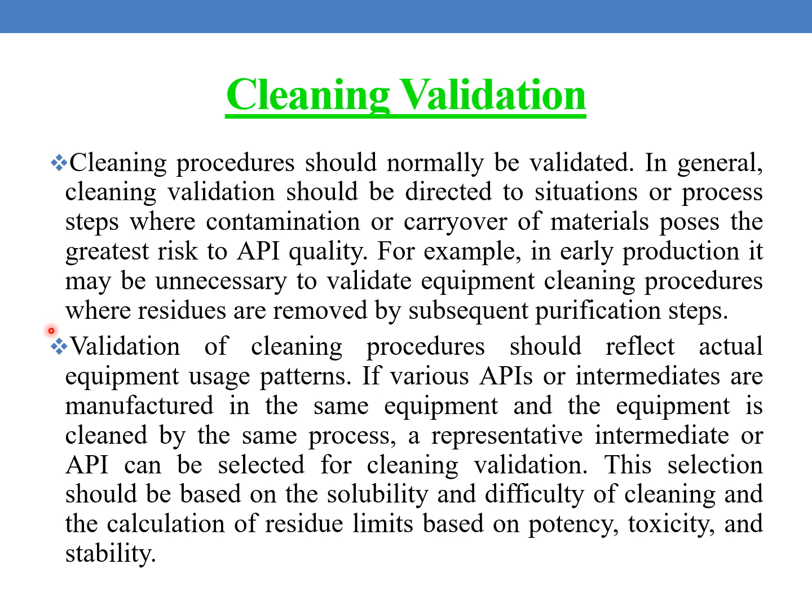If various APIs or intermediates are manufactured in the same equipment and the equipment is cleaned by the same process, a representative intermediate or API can be selected for cleaning validation. This selection should be based on the solubility and difficulty of cleaning, and the calculation of residual limits based on potency, toxicity, and stability.